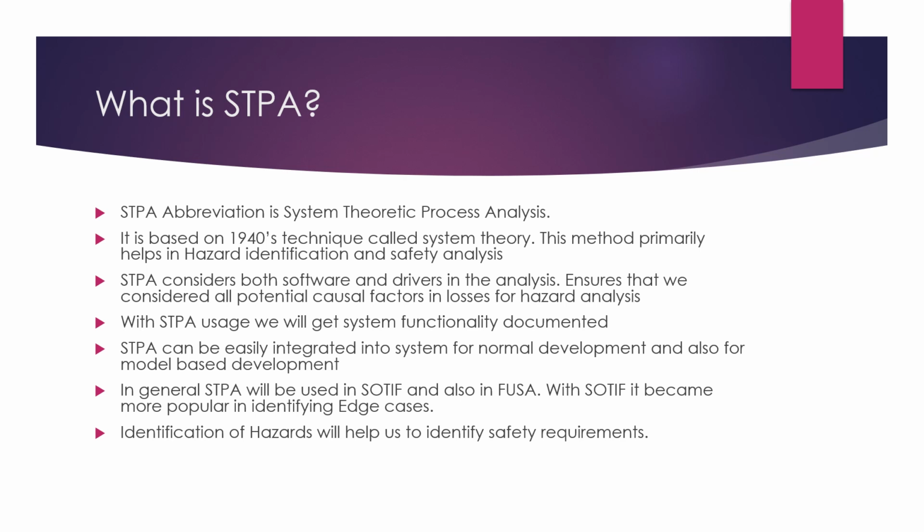As we discussed earlier, if we introduce STPA from the concept phase during hazard identification, it makes us identify a lot of hazards, which leads to safety goals, which leads to safety requirements, and we will avoid a lot of failures in the automotive system.